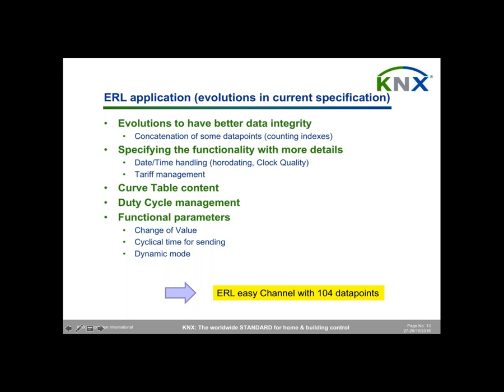Important information: the duty cycle management, because we have in this device regular sending, cyclical sendings, and you may reach the duty cycle of the RF specification. And for this, it has been specified in the application how to react to this duty cycle limit.